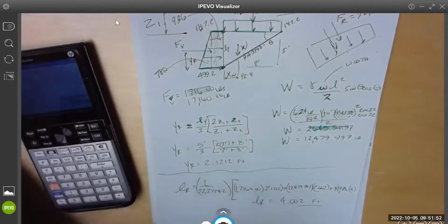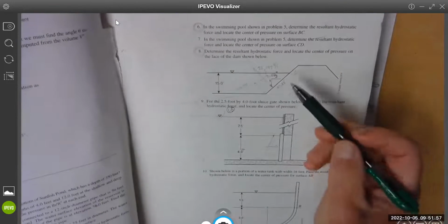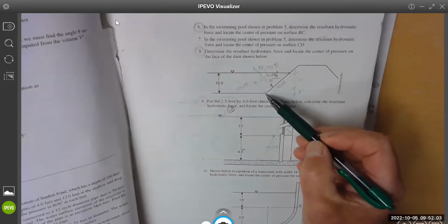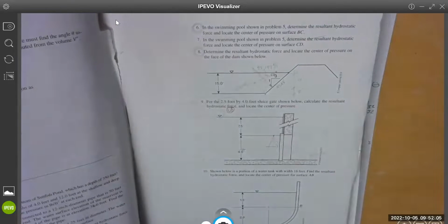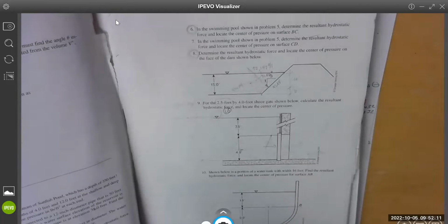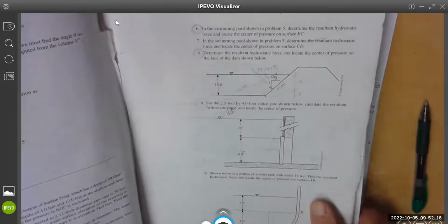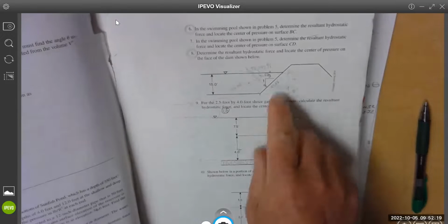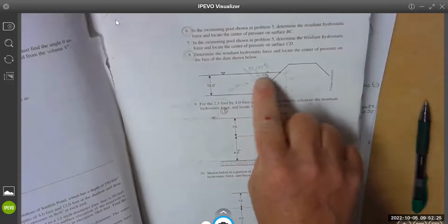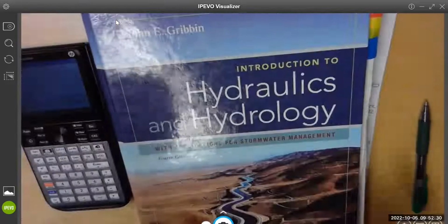So for that one, when we're finding the Z, we're not gonna do the y over 3 times 2z1 plus z2. You'll have to look at your pressure curve. It's gonna look a little different because it's 0 at the top, not a trapezoid. It'd be 1/3 z. But it's at this angle, so draw your load curve off at this angle where it's 0 here. You can see this pencil-sketched load curve there.